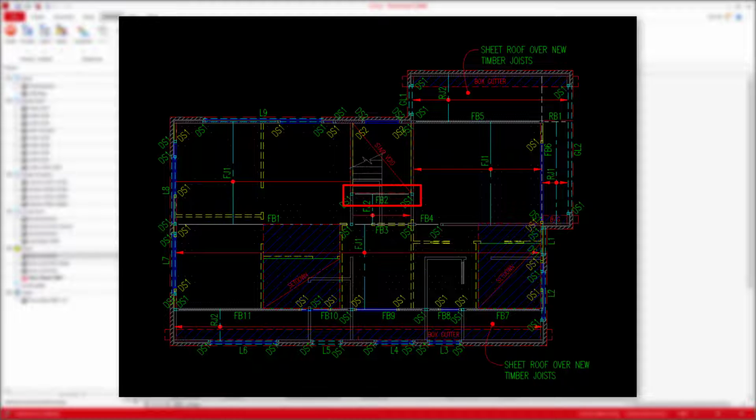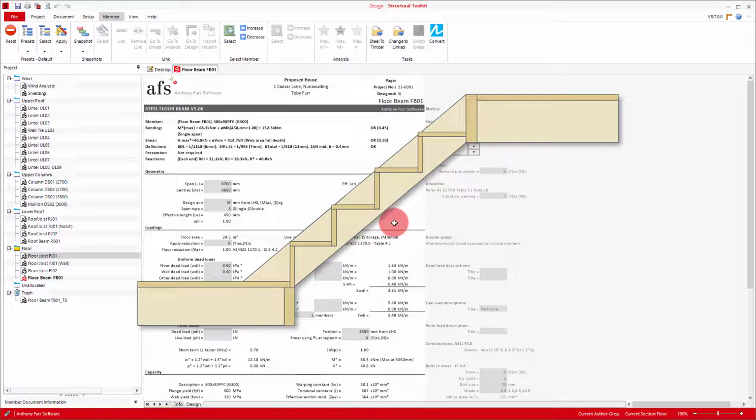Our next floor beam design is a little different. FB2 has some floor joist loads like with our FB1, but it also may need to support some stair load depending on how the stair builders decide to frame the stair. Usually a stair like this would have timber risers and treads that form the steps, which are then supported on either a wall or an external stair stringer.